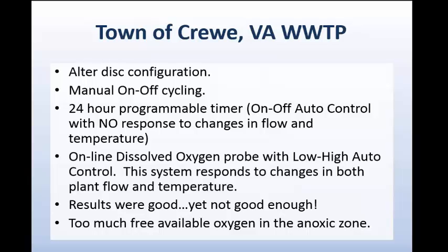We had an online dissolved oxygen probe that has high and low controls, and with that linked into the rotors to cycle from low to high, we found a system that responded to changes both in plant flow and in temperature. It's a simple set point control system.